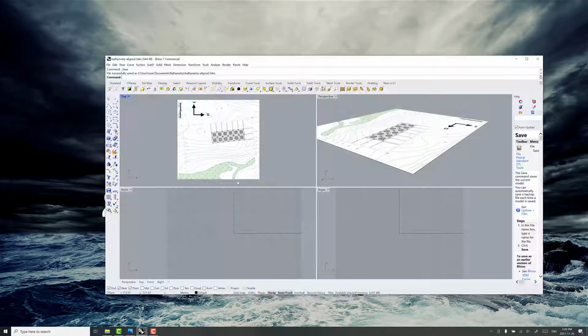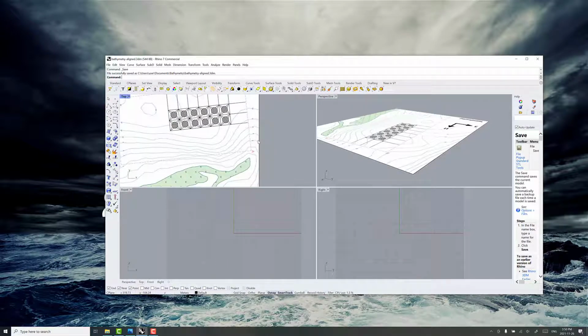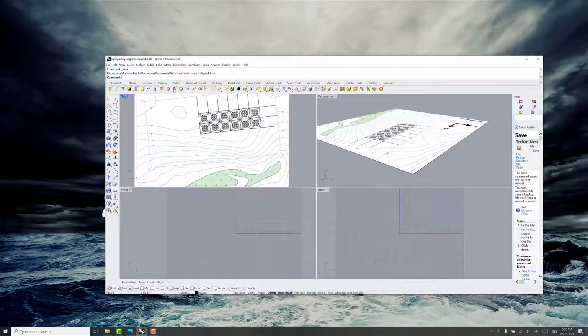Previously, we imported this into Rhino, oriented it so that the north lines up with positive x and east lines up with positive y, so that the mesh we generate will line up to the ProteusDS coordinate frame. It's also to scale. The next step, what we want to do is create some polylines that trace along the depth contours that are indicated in the plot.